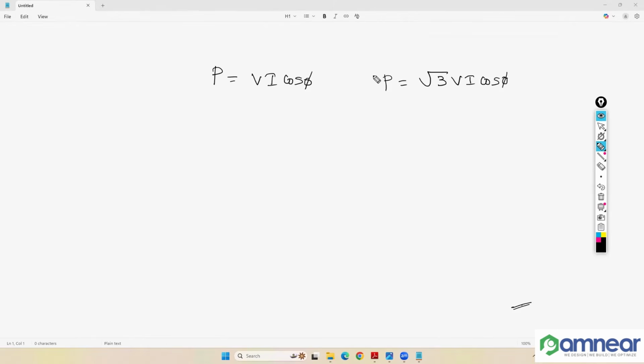So this is a 3 phase load distribution schedule. Here I have to calculate the load current for the 3 phase. What is the power equation? Power in watts is actually root 3 VI cos phi. Then power in kilowatts, because the actual total load we are getting is in kilowatts as per the load distribution schedule. So we have to form an equation for the load in kilowatts.